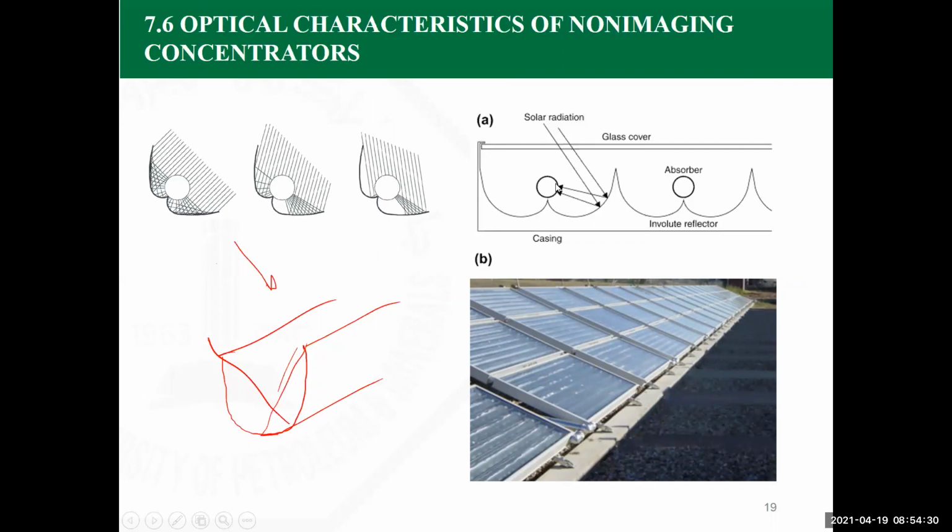We have seen before that when you evacuate the cylinder from inside, and you have a couple of cylinders with the fluid passing through, then having this part evacuated, a vacuum, means that we are eliminating convection and conduction losses. Accordingly, you can get better performance, more energy falling into the unit and less energy loss from the fluid inside, or the pipes inside, or the receivers inside.